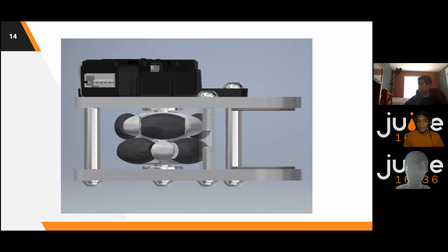So yeah, that's pretty cool. I think one of our slightly prouder moments was that we were able to park autonomous with only 3 wheels, because we were able to correct for the XY rotation with our PID system. We actually put a screw into a gear, and it stopped our back left wheel from turning, but it was still able to go straight because it just applied a lot of power to the left side versus the right side to fix the correction issues.